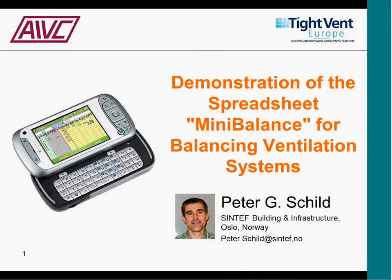This is a very simple sheet, and it can, in principle, be used on any smartphone that can open Excel spreadsheets, and can also be used on laptops, etc., on the building site. Of course, it uses the proportional method of balancing, which means that you use it for balancing CAV, or constant air volume, air terminals that have to be adjusted and fixed. It's not for adjusting VAV air terminals. So I'll just demonstrate how we use this.